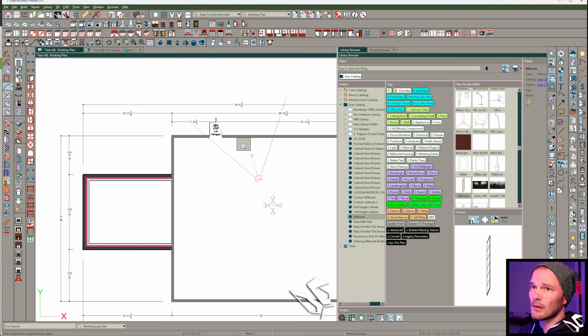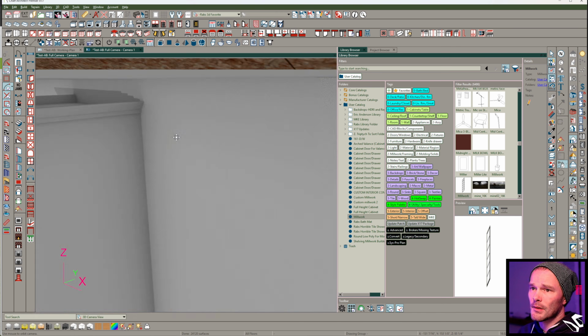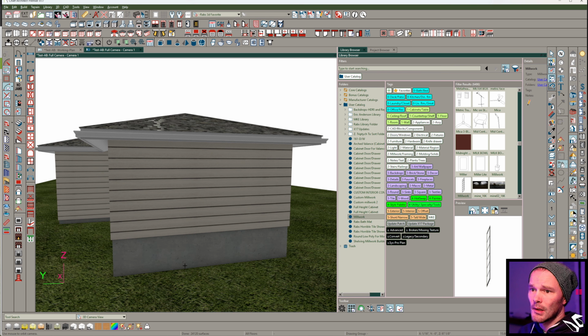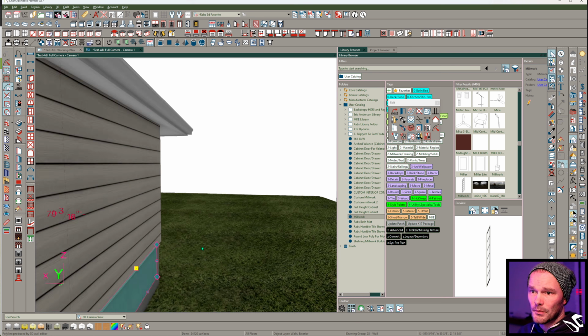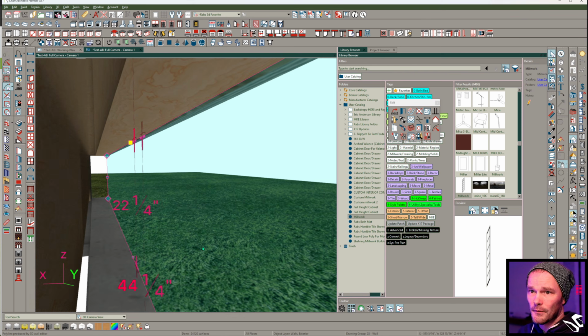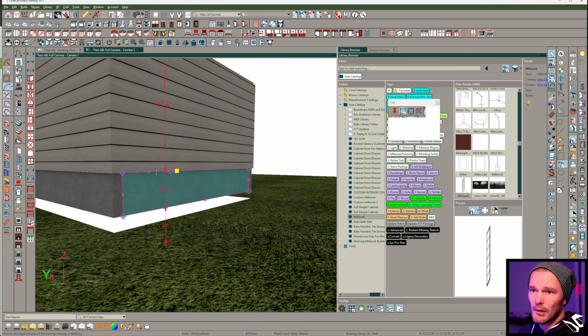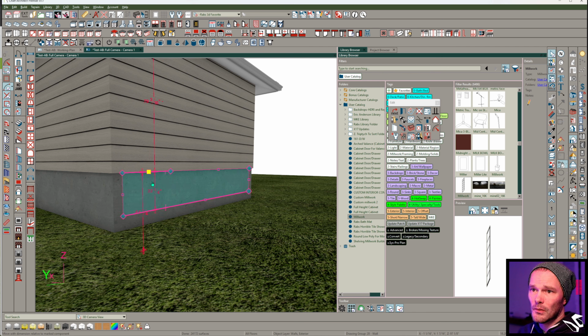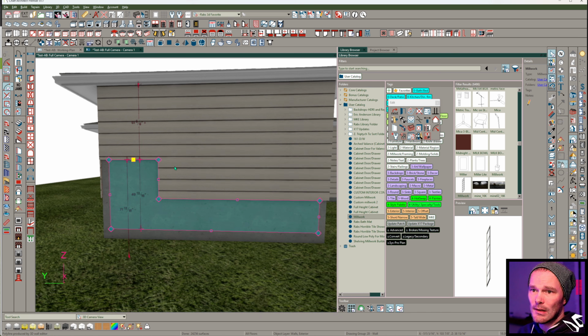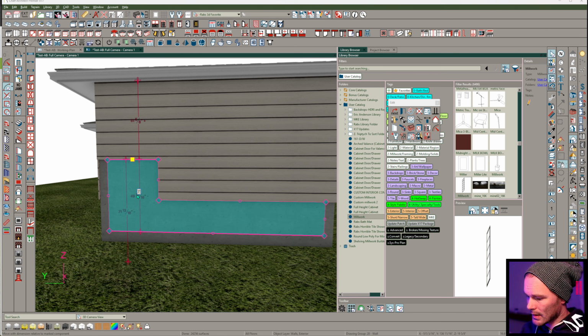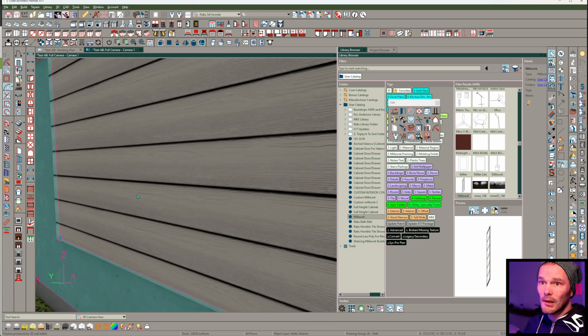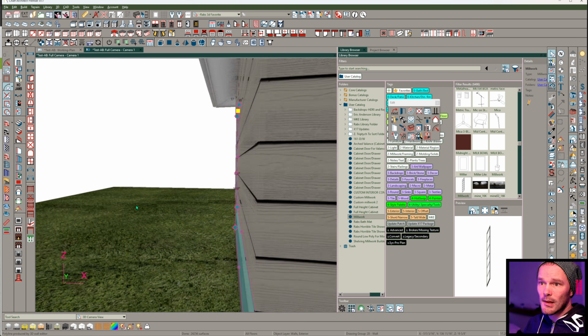And so if we go take a look at this side, this is just concrete pony wall, and it's a furred pony wall with framing, furring it out. And so it's easy for me to just use the break tool and slide this up to whatever I want. And you know, with 3D dimensions it makes it even easier nowadays. So here would be that 7 foot. And you can see everything's looking correct on the inside.